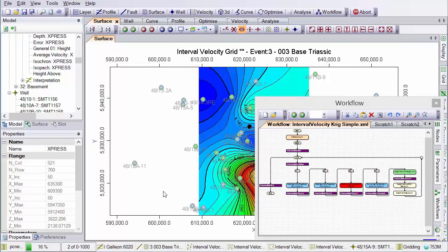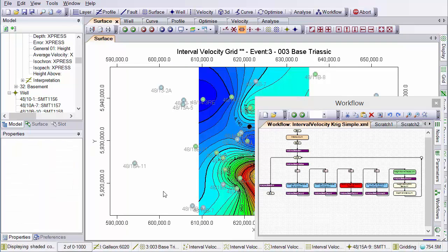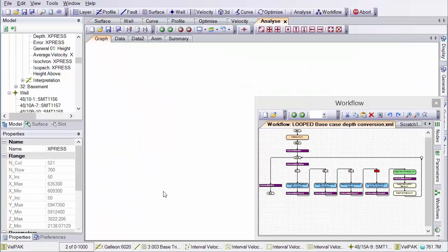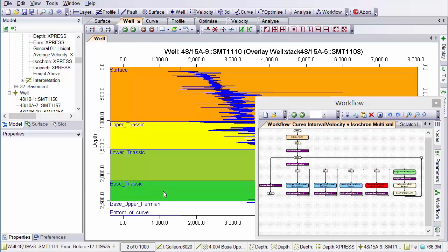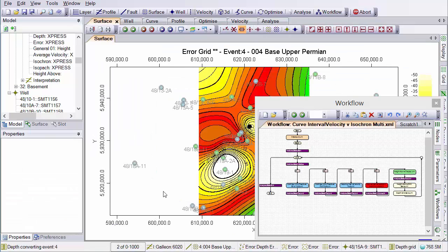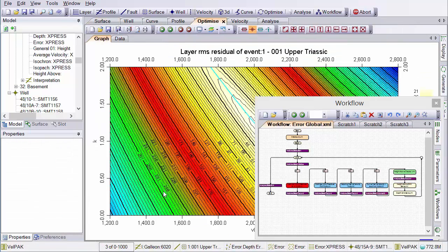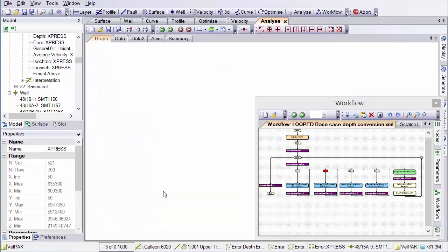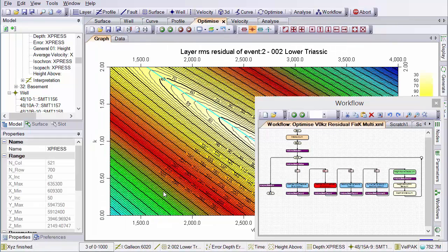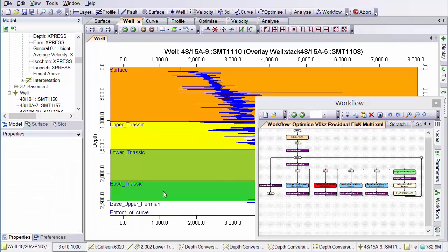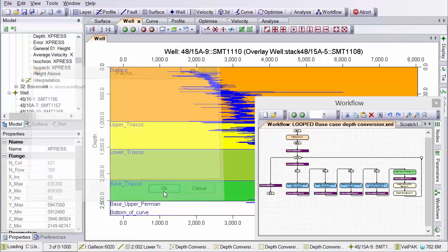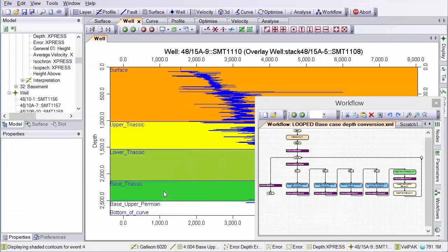Ordinarily you'd run the work job in batch mode, whereby the job is divided up by the number of CPU cores you nominate to use on your machine. So on an 8-core machine, the elapsed time would go from 16 hours down to about 2 hours. However, even that is too long for this webinar, so I've run the job already and can load the model now. So I'll hit escape to stop this job, and I'll reload my previously ran model.